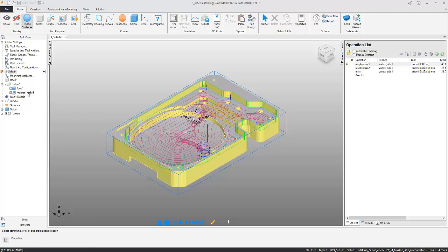A side feature gives me more versatility because I can cut the inside of a curve or the outside of a curve. I could even cut an open curve, but understand if you use an open curve with Vortex, you're going to get no toolpath. But I'm talking about closed curves here. With my Vortex, I can go either way with a side feature. If I were to define this as a pocket, then I could only apply the pocket attributes to other pockets. So I would be limiting myself a little bit that way.